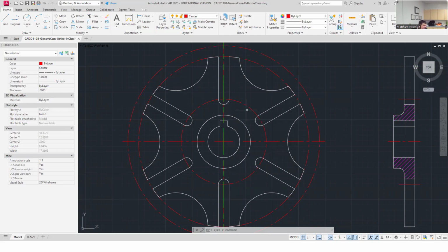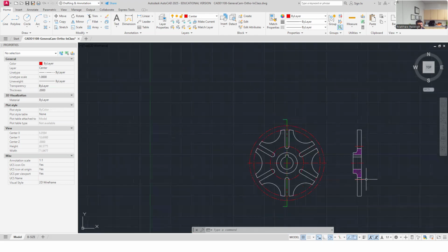But not always, right? We've done some slots where I haven't carried the center line horizontally through the slot. I carry it vertically, or I carry it in the plan or the top view of it when I'm looking at the slot. I would always carry a center line through here generally when I look at it this way, but I don't always carry it when I look this way. So I have it on the example that I've shown. Is it necessary? Maybe not. So I'm going to just leave those three.